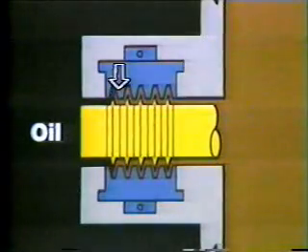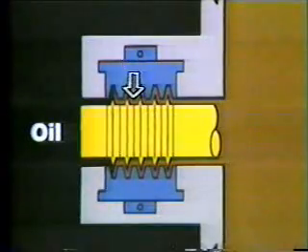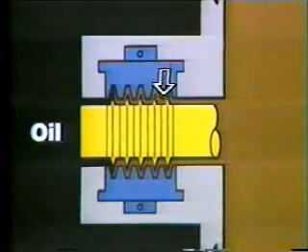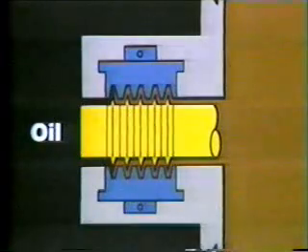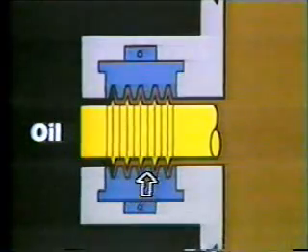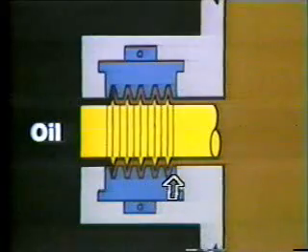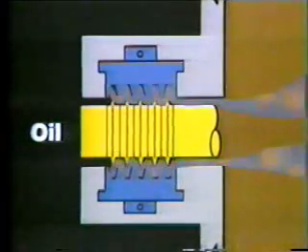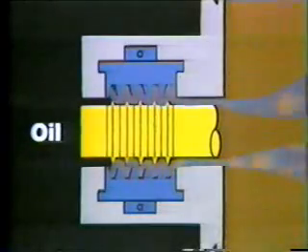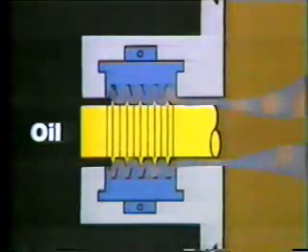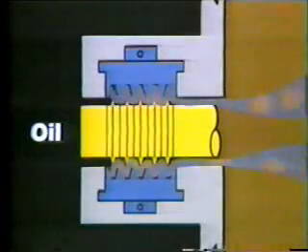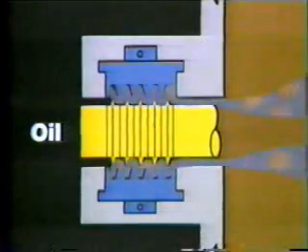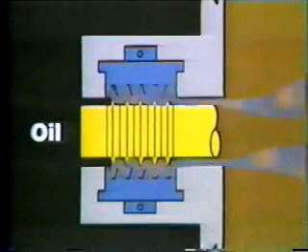The labyrinth seal consists of a series of soft, razor-sharp teeth aligned against another piece of metal. These teeth are made of soft metal to prevent them damaging the other parts of the seal. Oil is on one side of the seal and air is on the other side. As the air flows through the compartments of the labyrinth, the pressure drops and velocity increases. The high-velocity air escapes from the labyrinth, returning excess oil to the oil tank.